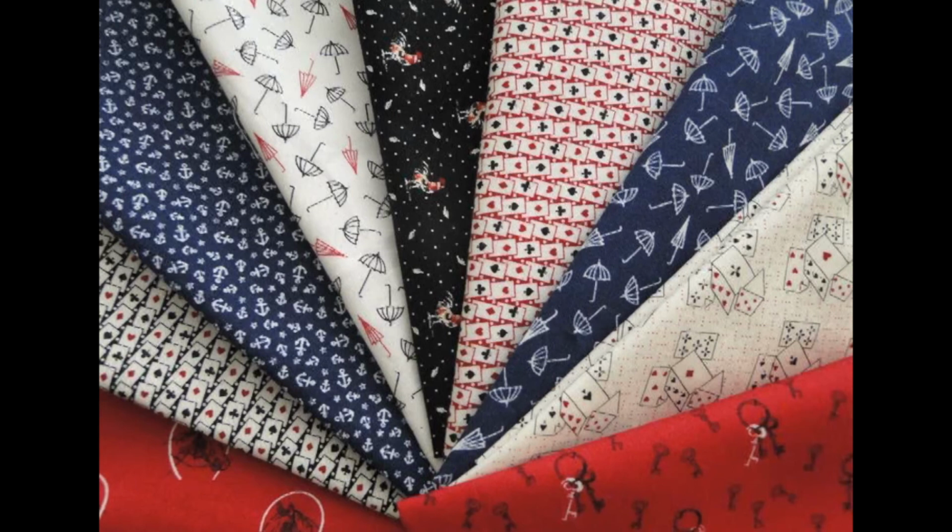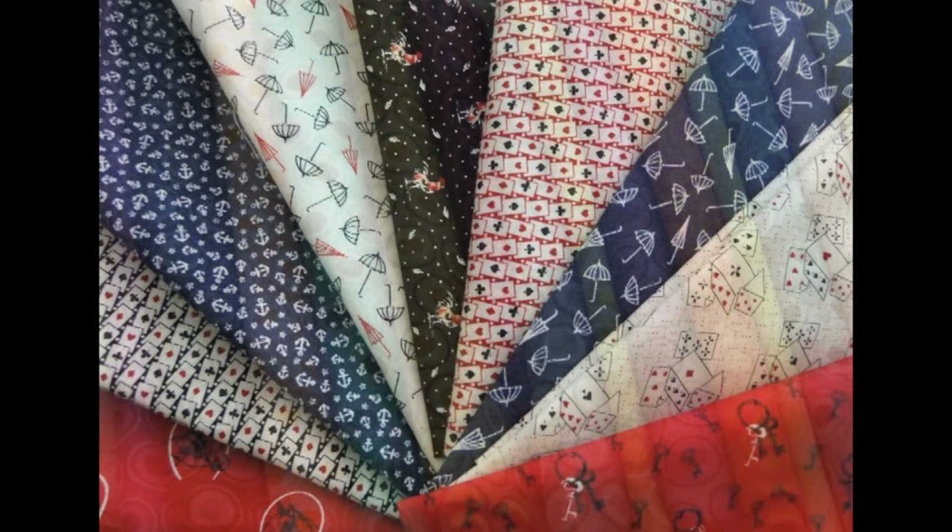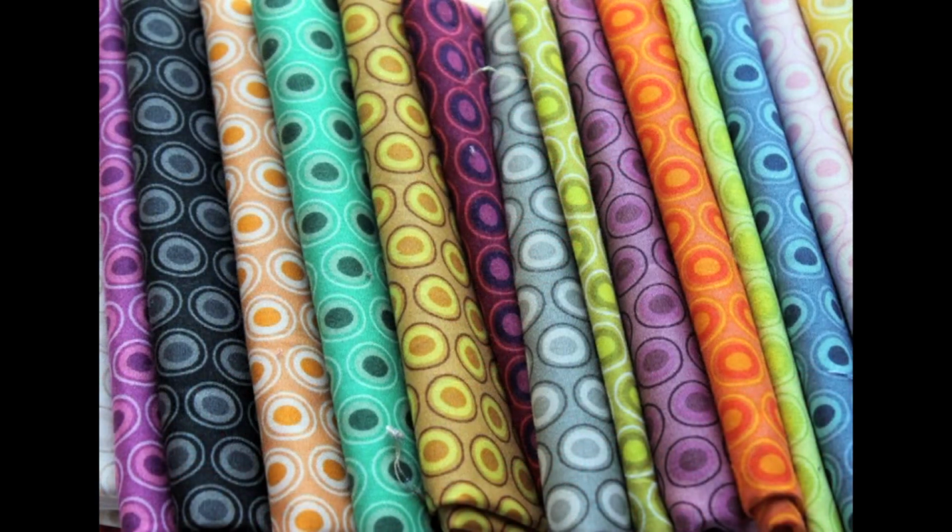And in case of synthetic fabrics, actually this pre-shrinkage and other things are not there, but they are finished at a very high temperature, which is equal to their transition temperature, so that if you use any temperature more than that, the fabric is going to distort. And so when it is set at that particular temperature, when the garment is cut and stitched, then it will not lose that particular shape. So for synthetic fabrics it is okay, but woven fabrics of mainly cotton and rayon and also wool pose problems during wear. And so shrinkage should be taken as an important aspect, and fabric should be pre-shrunk and only then used for cutting.